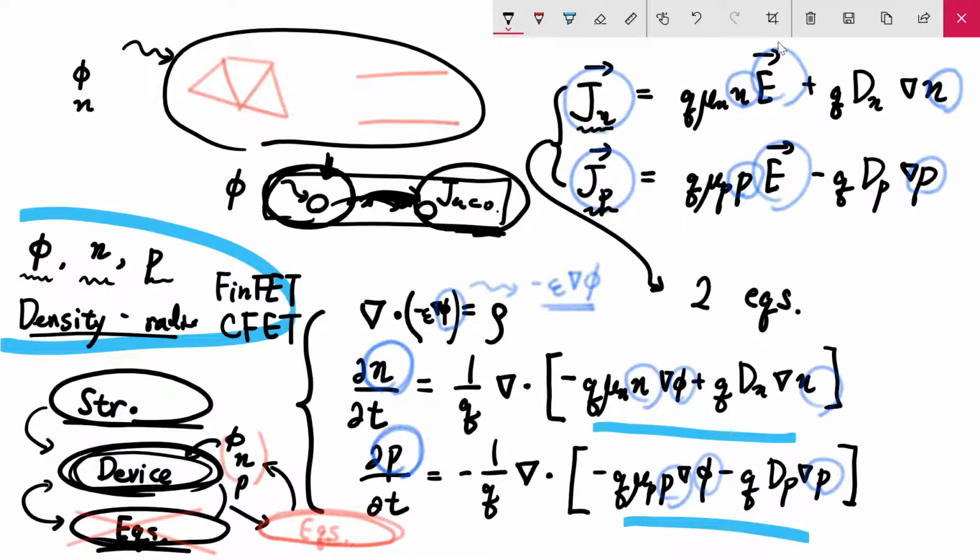However, if you add n and p as your unknown variables also, then the physical meaning of the second element in your unknown vector can change. Previously, for example, the second element of your unknown variable vector can be regarded as the phi for your second position. However, if you introduce electron and hole as two additional unknown variables and assign them like phi, n, p, phi, n, p repeatedly for each vertex, then maybe this second number, 2, can be regarded as the electron density for the first node. It is just one example. The assignment can be really up to you.